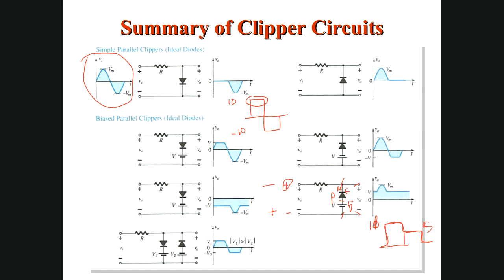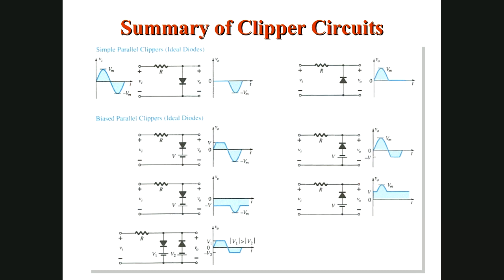Okay, now still we have not solved our question. In case of our circuit, our input is this. So we will do it again. Our signal has got two halves, positive and negative. So let us start from the positive half. In case of positive half, as discussed earlier, this is N and this is P. Your input is making your diode reverse bias, and your battery is making forward bias.